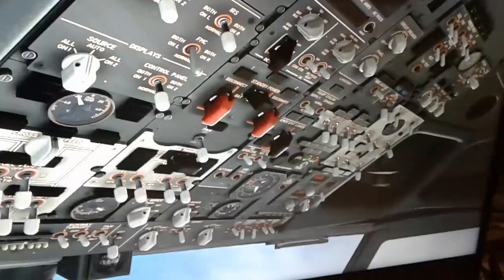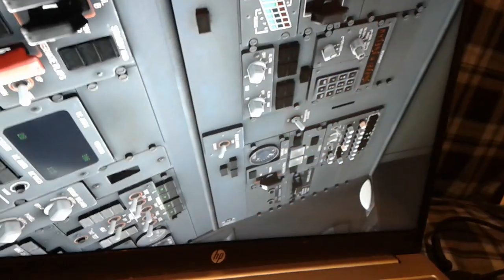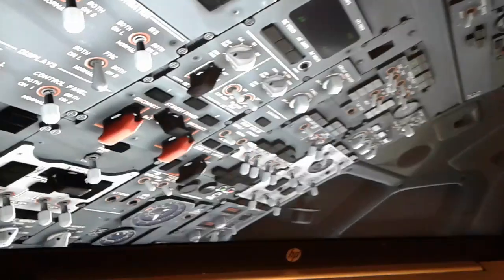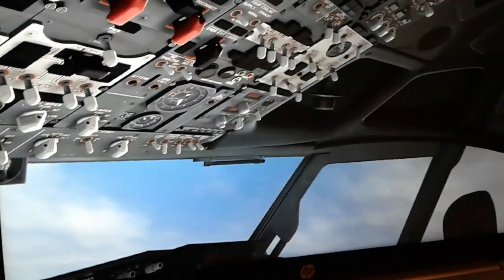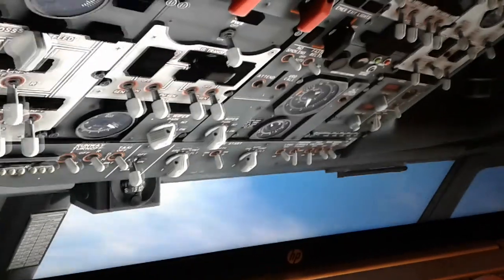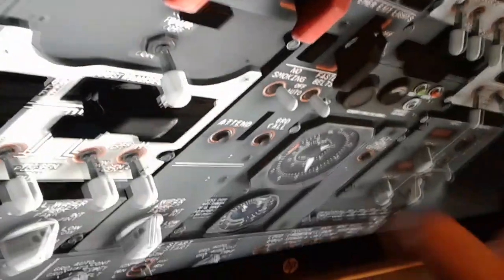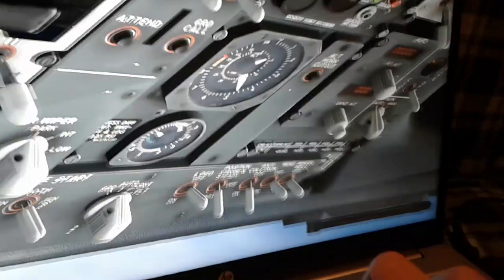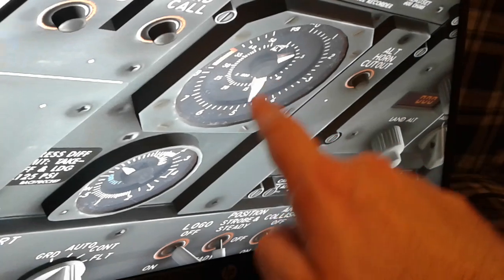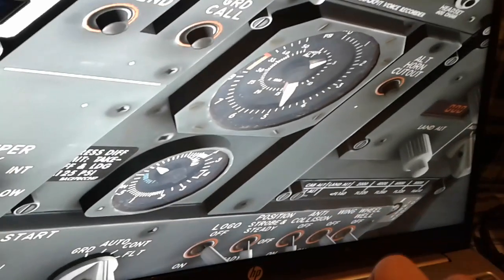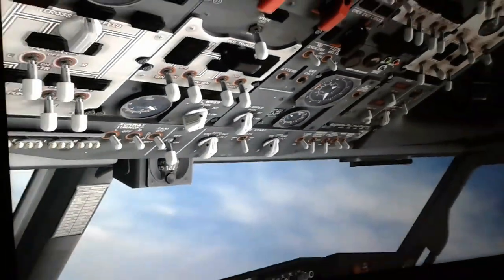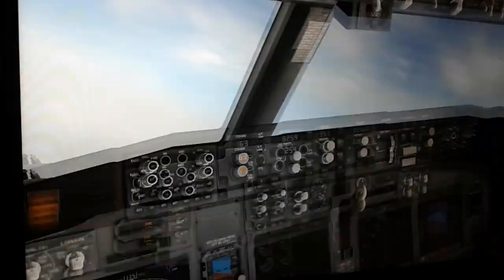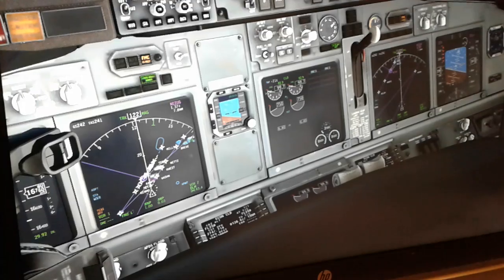So this is the cockpit, Boeing 737-800 after takeoff. You can see the panel over here, the ADIRU, other instruments. Cabin pressurization, the cabin has been pressurized. And now we have oxygen for the flight. You can see it's increasing, it's going to 5 psi. And now the outflow valve is closing. And also